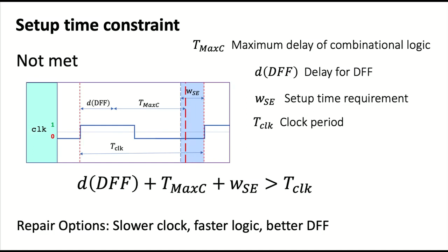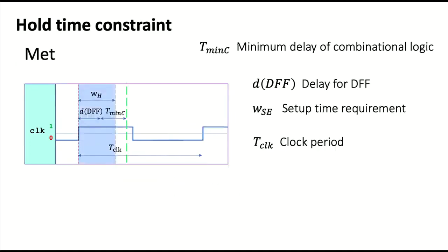Any questions on this? So this is setup time. People tend to understand setup time pretty readily. Hold time is a little bit harder to get a hold of. I get why there needs to be some hold time. You need some hold time, okay. All right, so here we are meeting the hold time constraint. This means that the flip-flop input did not change until this green line, and that was after the hold time expired.